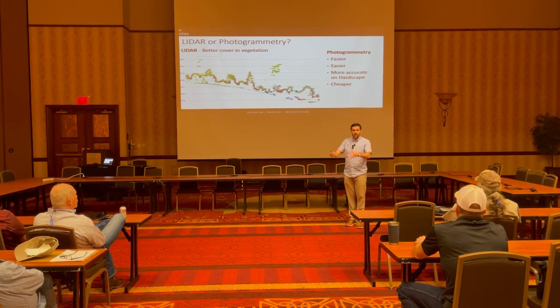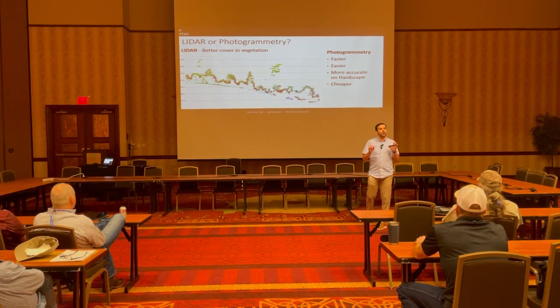If you ever see a ground-based laser scanner, then yes, it is going to be more accurate because that's on the ground and typically only going a few dozen feet from the sensor. But once you stick a LiDAR unit in the air, you have it wiggling around, moving, vibrating, and it's 200, 300, 400 feet away from the target, it actually winds up being slightly less accurate on hardscape.